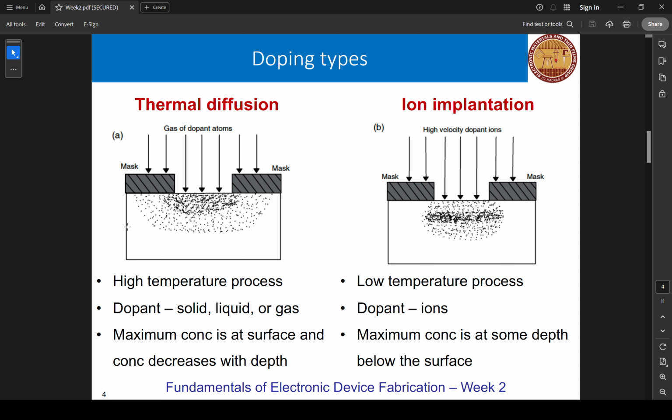See, this is a silicon wafer. So it's already doped, P-type or N-type, that we saw last class. It is doped during the growth. Sir, I am asking about solubility. If the wafer has more solubility, it can take more dopants. Yes. And if the dopant size is small, then the diffusion will be faster. So I get more and more dopants.